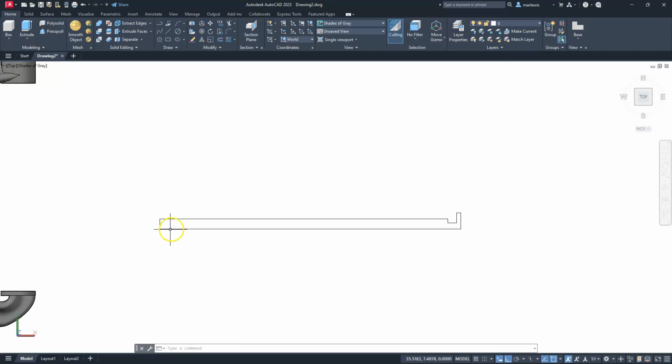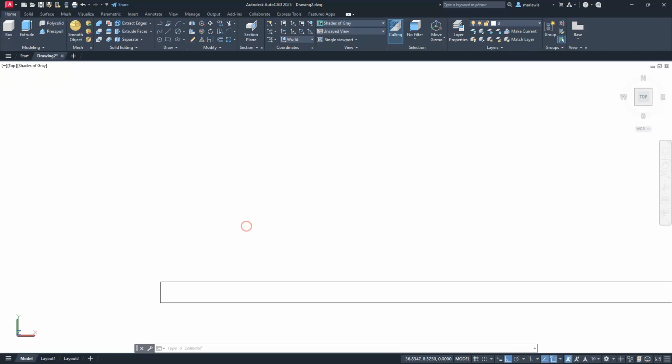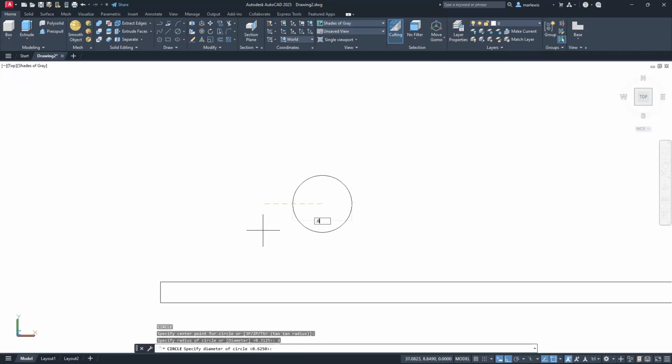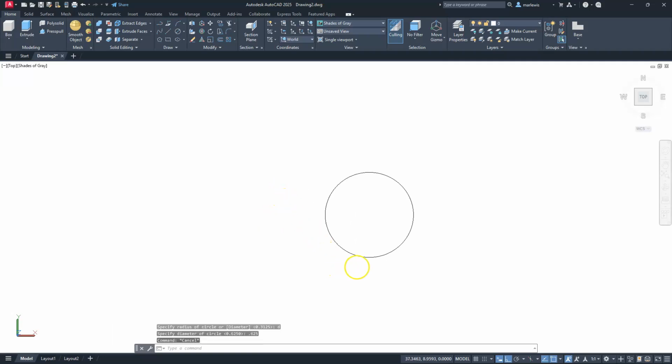And now I'll start working on what I have to do here on the top. So what I'm going to do here is I'll create a circle that has a diameter. So I'll type in D, enter, of 0.625 or 5/8. Let's go ahead and create a line straight up from this middle. Offset a distance of 0.25. All right, and then from here I can just create a rectangle, and that'll be what I need to kind of finish this part off.